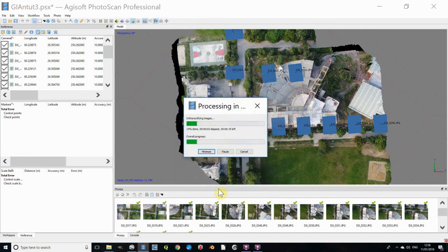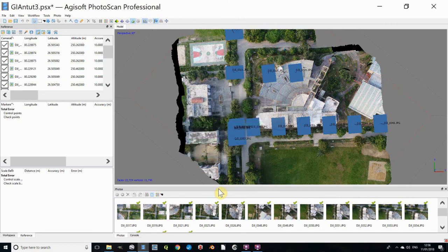It's going to orthorectify the image. This can be a bit more demanding, but it's going quite well because there's only 15 images. And certainly if you have a large data set with hundreds of drone images... And note, this will work even if you have images that are looking sideways on buildings. You will still get a good map.